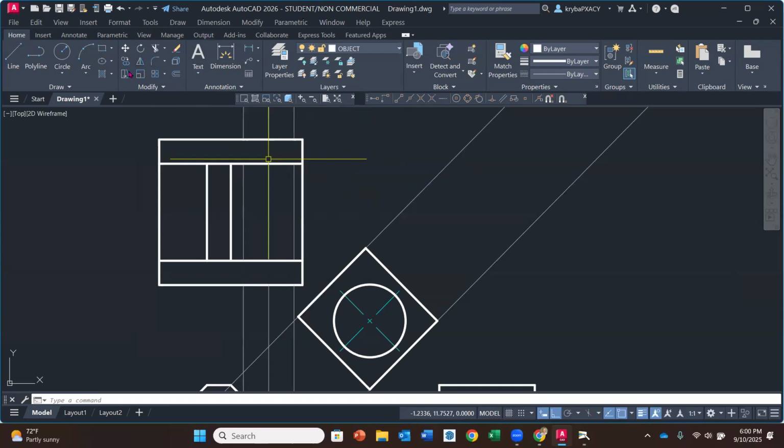So now I'm going to go to my ellipse command just to the right of arc. And I'm going to start in the middle one at the midpoint. I'm going to go up to or to the right, and then I'm going to go up. And I don't want it to grab that edge, so I'm going to key in 0.75 again. So it's the width, it's the radius of the 1.5. Okay, so you should have, if you would, kind of a vertical egg here. Okay.